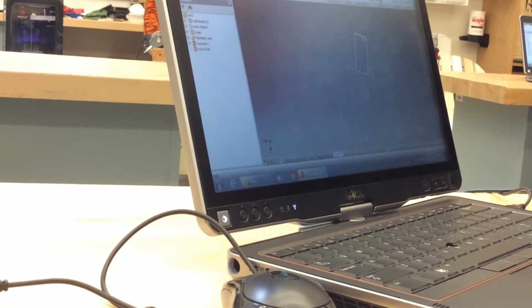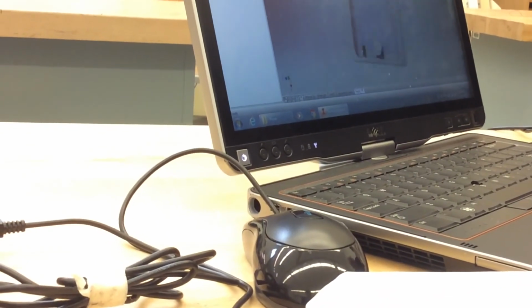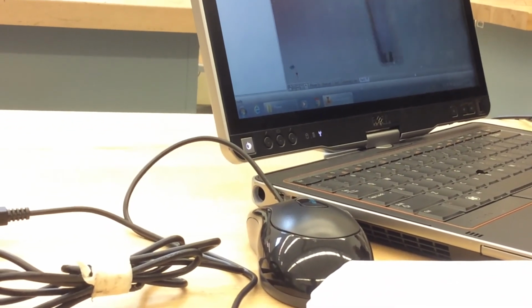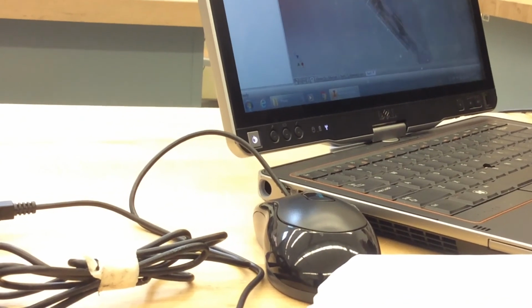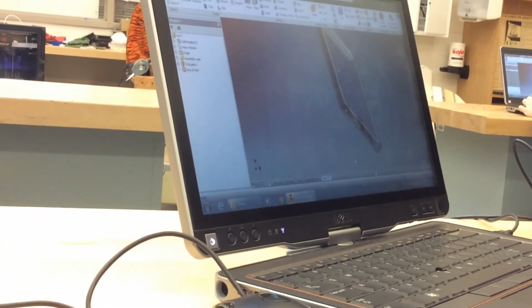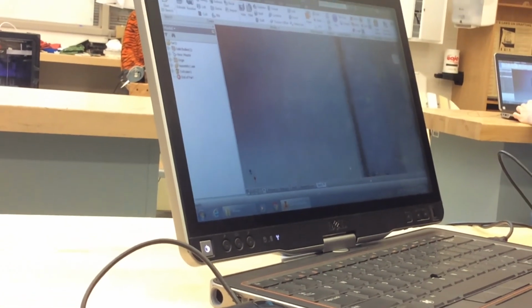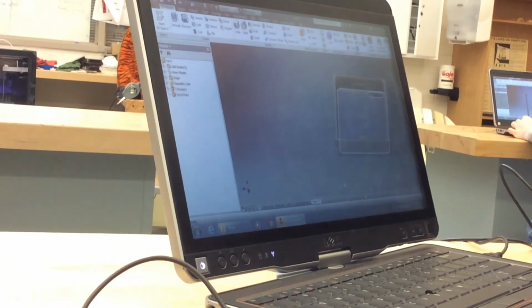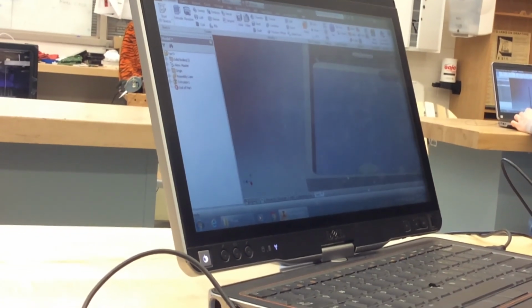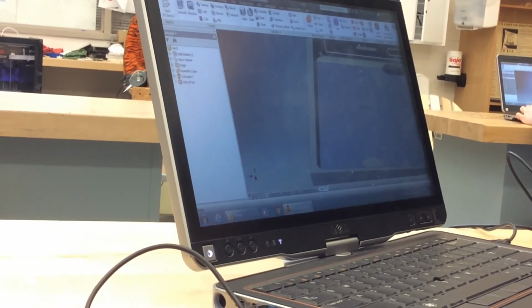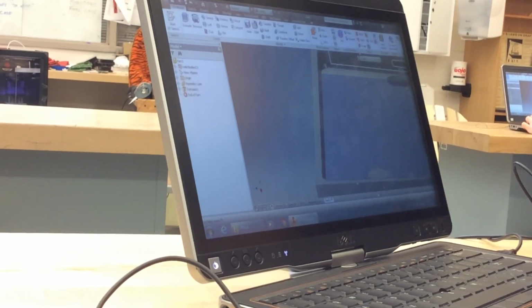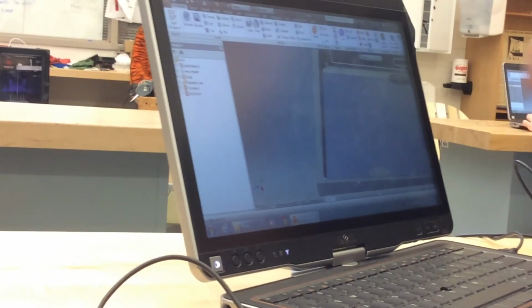And now you can see everything from the inside of this phone. So you can see like the holes for the speakers they have here at the bottom and the plugs at the bottom. All those indentations. Now you can project all of that geometry for all the rest of your slots. And you do the same thing like you did for the side. Yep. And then you should see something in the top here, where you see like the SIM slot here. All right. Yes. And then you guys know how to clean all that up. Yeah. Good. It's the same thing as when you take off the